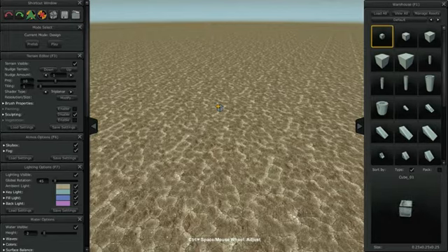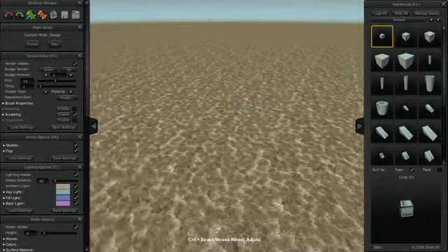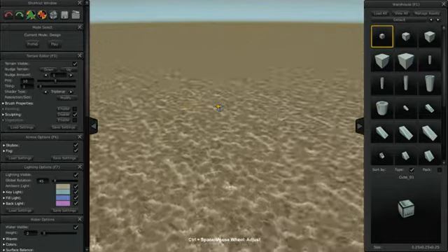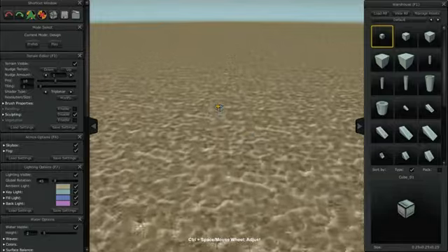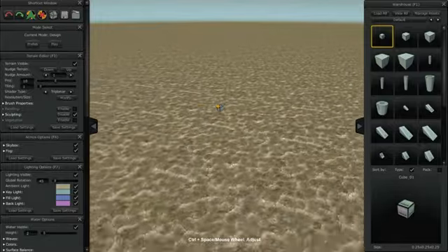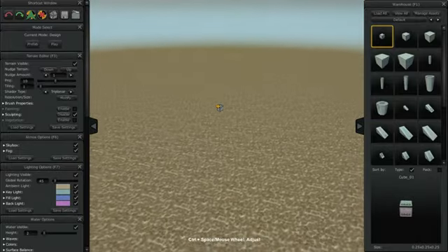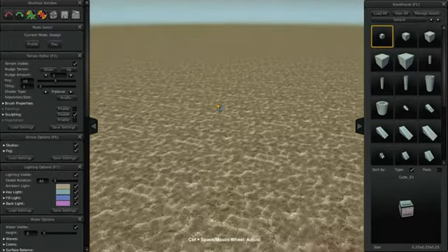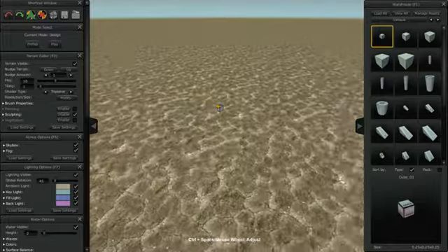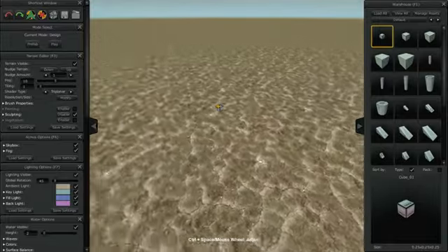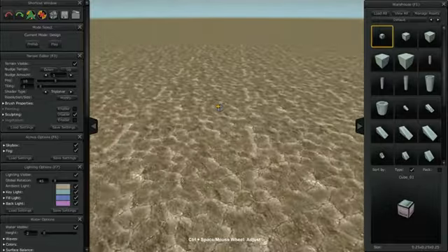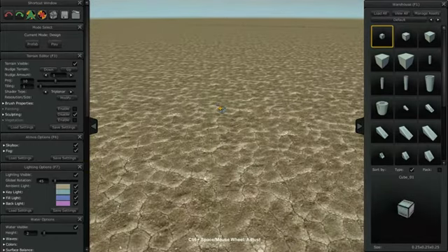It is possible to fly the camera around the environment by using the WASD keys in combination with the arrow keys on your keyboard. Use WASD to translate the camera and the up arrow to move the camera up, the down arrow to move the camera down, and the right and left arrows to turn the camera to the right or the left. To expedite workflow, AGF is designed with a radial menu system.